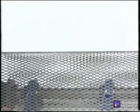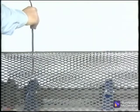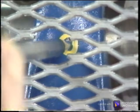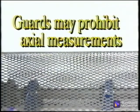thrust. Pillow block bearings on shafts like this may be inaccessible due to guards, covers, or simply be out of safe reach. If the guard is mesh, the long stinger may be used to reach through it for the radial measurements. Although the stinger or long probe does not provide the best data, it is still far better than no data. However, it is important to collect an axial measurement on each pillow block bearing, and the guards or covers